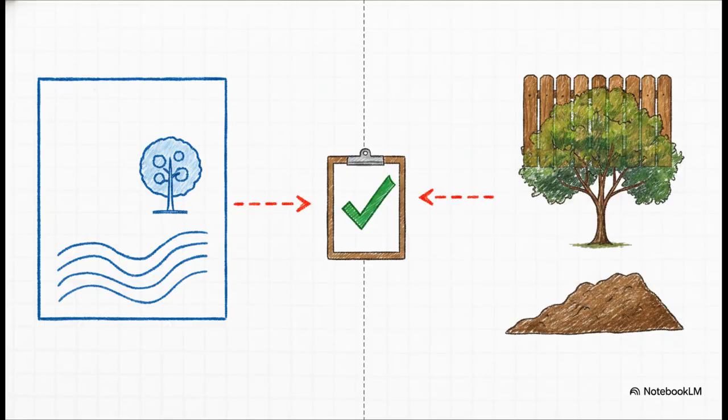Okay, so now we have the right plan, and we're facing the right direction. It's time to fully shift our focus out to the physical terrain. We need to translate that 2D drawing into a 3D environment. This means you have to physically walk the bounds of the site to cross-reference the paper against the reality of the block. You're verifying boundaries and dimensions, existing structures, contours, and datums. You're looking out for significant trees and noting any easements where building is a no-go.